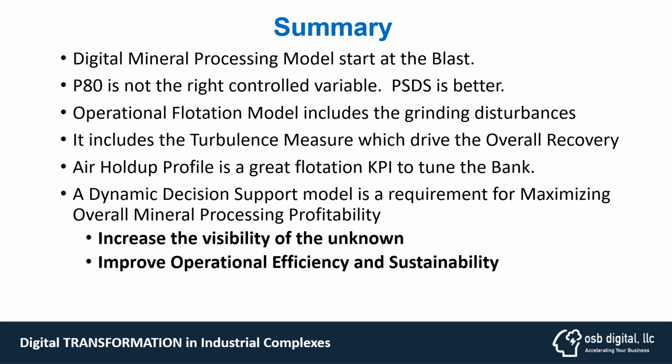The operational flotation model includes the grinding disturbances, as you just saw in my presentation. It includes the turbulence measures that we have for every flotation cell, and we use that as a specific energy consumption that drives the overall recovery. This generates the right air holdup profiles that we can calculate in real time, and we can manage those KPIs to tune the flotation bank correctly, looking in real time at the losses of copper, the recovery based upon the profiles of air, and the most important thing is the right size distribution.